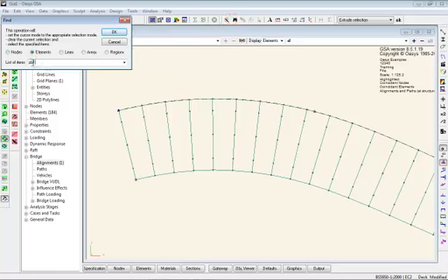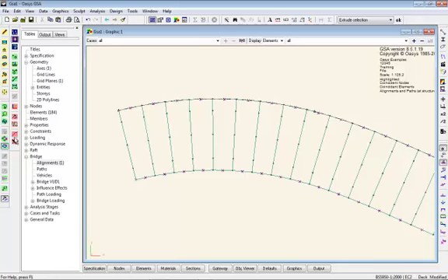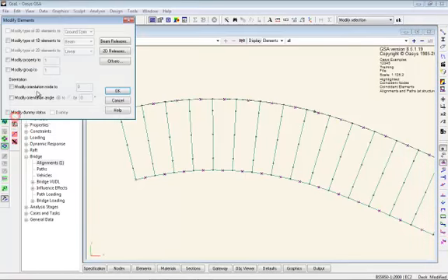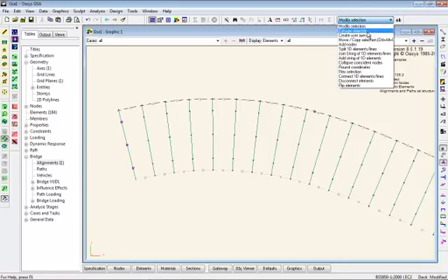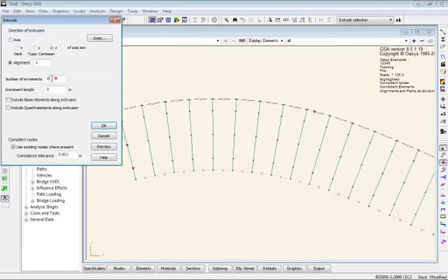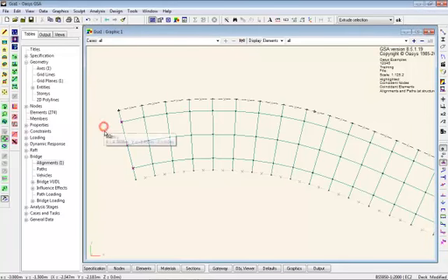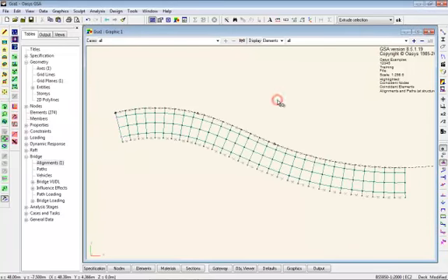And I'm just going to select property beam 1, which is those edge beams, and I'm going to modify those so these are dummy elements. So they'll make grid panels, but they won't have any structural strength. And I'll pick those 3 nodes, extrude those along in 30 meters, 3 increments, and there we have our basic geometry made for the bridge.